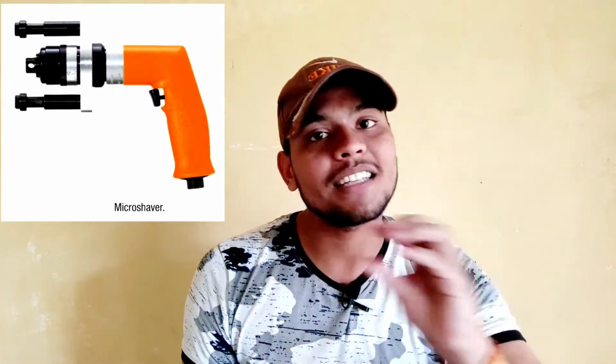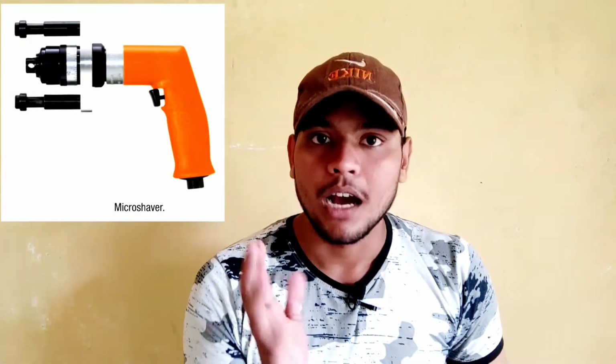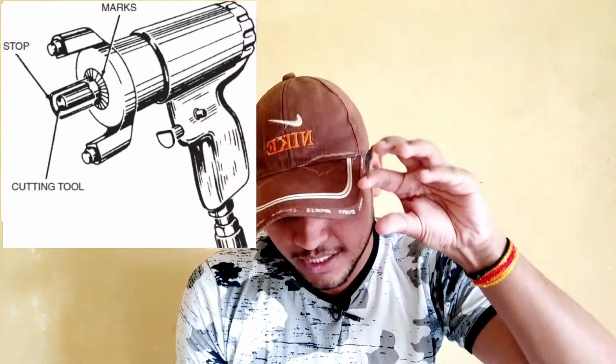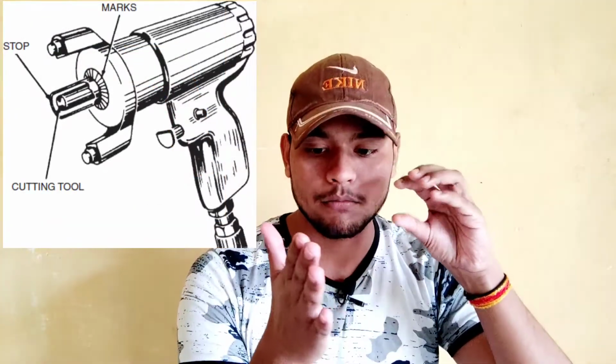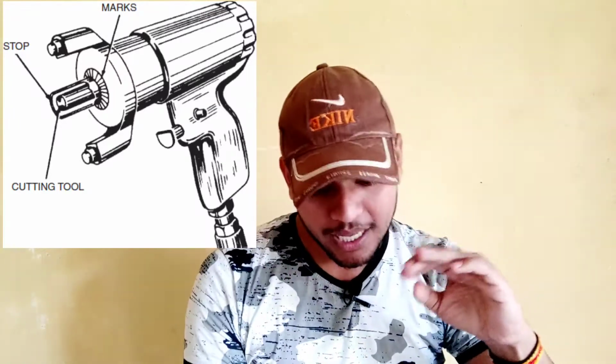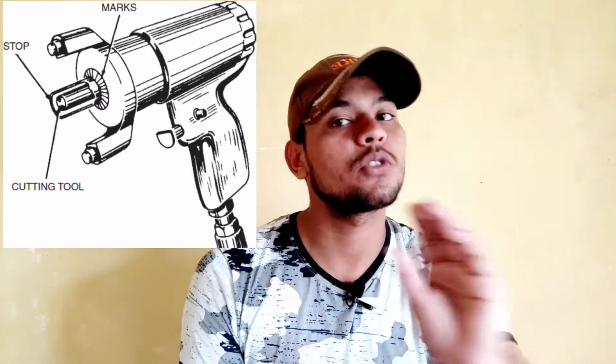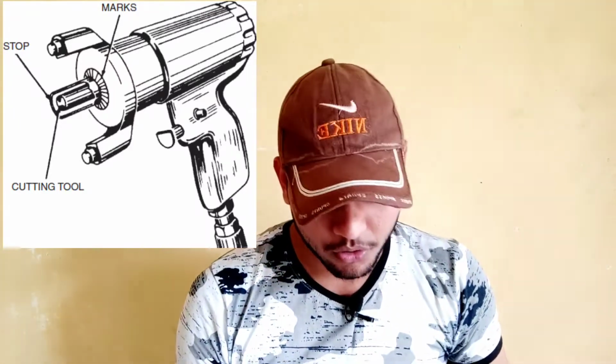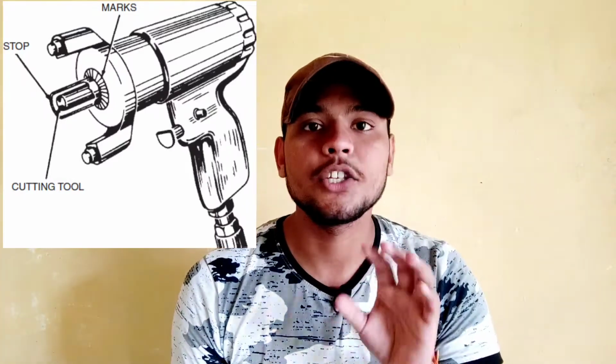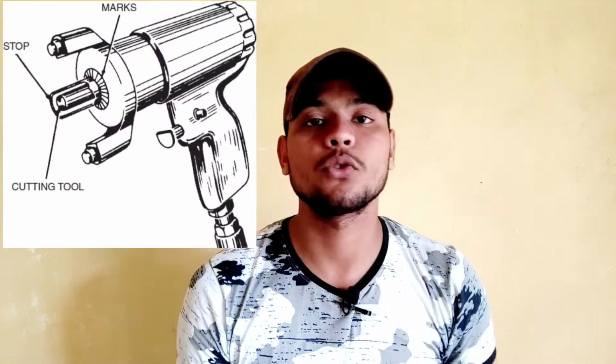How? They cut the extra rivet from the skin. They have three parts: two legs that stabilize on the sheet, one stop so that not too much material is cut out, and the third is a cutter to cut out the extra rivet from the sheet. They are basically used to make the skin smooth so that the aircraft feels less drag.